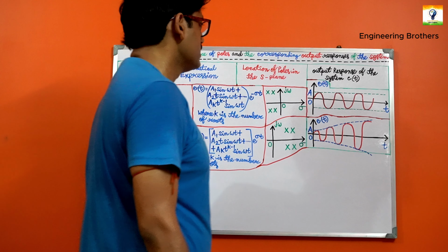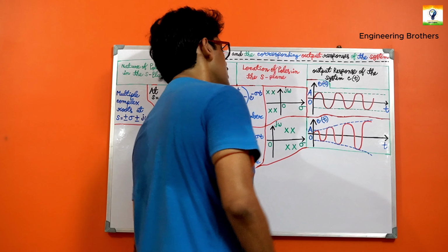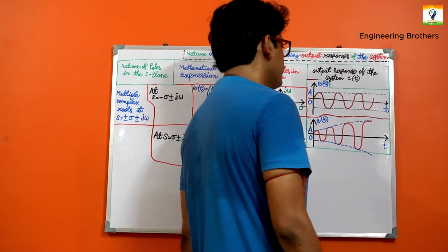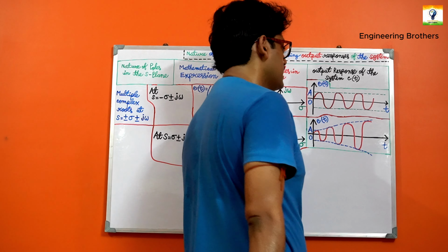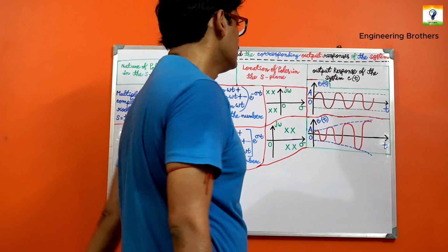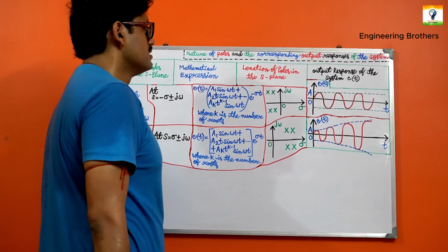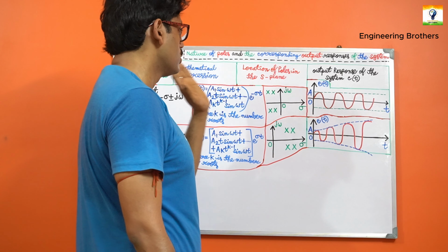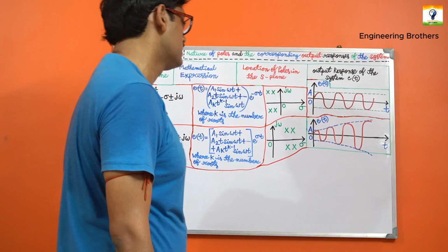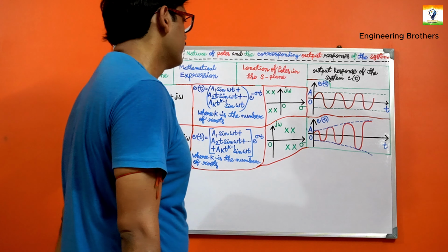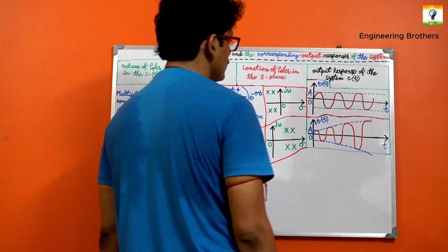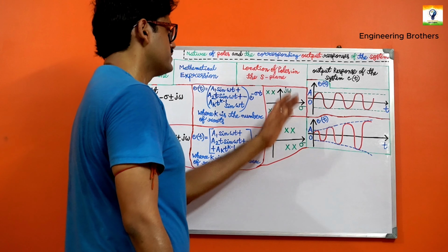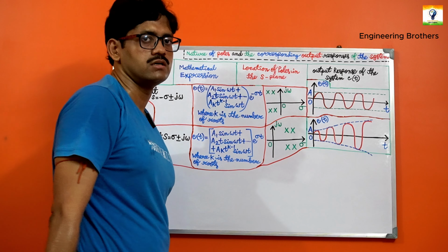As you can see, the poles are on the left hand side of the s-plane, but the waveform still has a constant oscillatory characteristic. That is why we can say the system is marginally stable. Just by the location of the poles, we would say the system is stable, because the poles are on the left hand side of the s-plane.